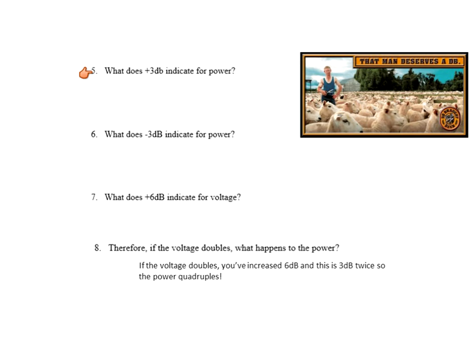Not voltage now, we're talking about power. So a positive 3 decibel number means I'm going to double the power, no matter what the original power was. I can have 2 megawatts, but if I increase 3 dB, I'm going to have 4 megawatts. I'm multiplying it by 2.